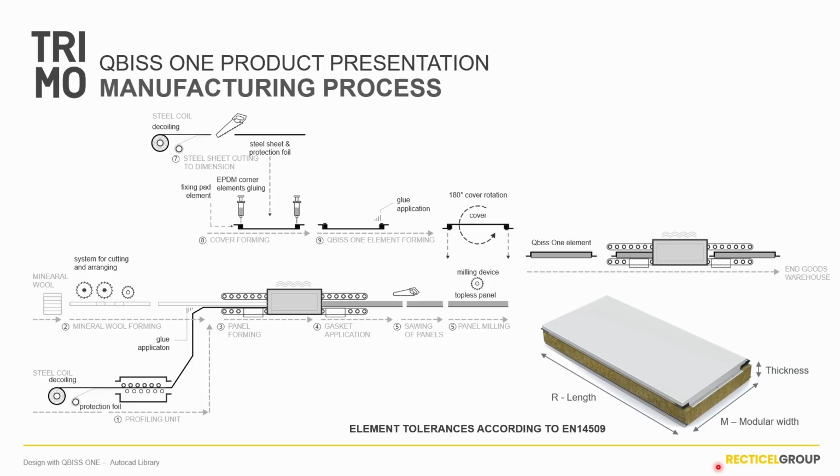What's important is that steel coil width is procured according to the widest project module. Therefore, any smaller modules mean additional production line setting, cutting procedure, as well as additional material wastage. And this results in higher final cost and is related to the previous slide when we talked about the cost optimization with fewer module sizes.